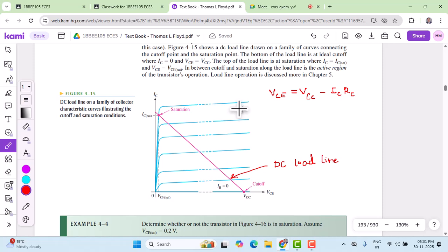So IC is very much less than IC max. IC max is 100 milliampere, given. IC now what we got is 19.5 milliampere. So this will not change the VCC value, of course, because VCC applied will be nominal value itself. It is determined by only IB and beta DC.